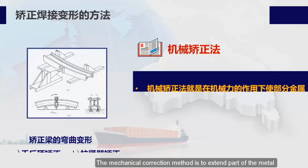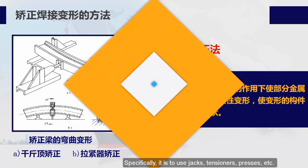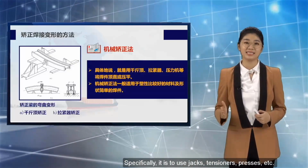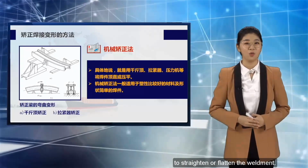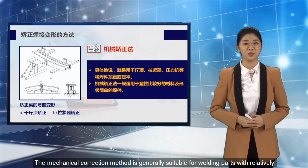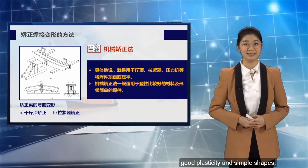The mechanical correction method is to extend part of the metal under the action of mechanical force, produce tensile plastic deformation, and restore the deformed component to the required shape. Specifically, it is to use jacks, tensioners, presses, etc. to straighten or flatten the weldment. The mechanical correction method is generally suitable for welding parts with relatively good plasticity and simple shapes.